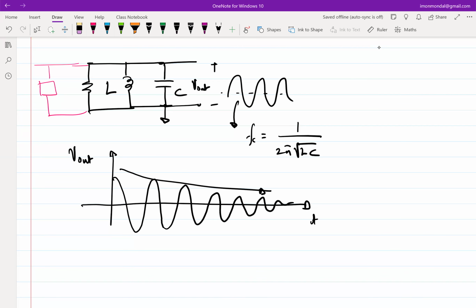So let's say since this is in admittance, let me call this G. And if I can only get a circuit which gives me negative of G, then summation of, if I club them together, I'm good, right? Yeah, this is fine. So admittance will go to zero. So now the question is, how do I generate this negative of G?